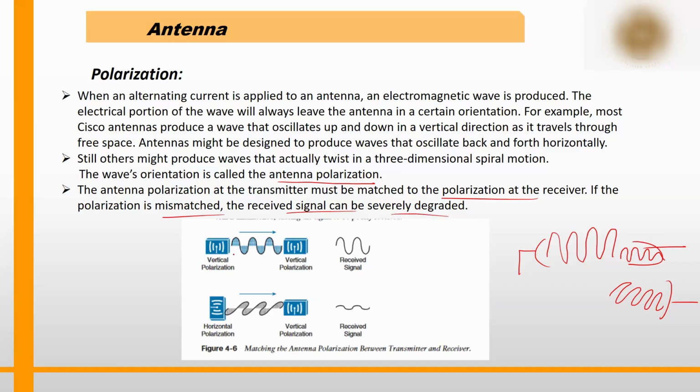So this is a vertically polarized signal, up and down like this. And this is sideways, horizontally polarized like this. So when you are sending the radiation, you can polarize it accordingly. Just remember the first session where you put a finger into a pond and it creates some ripples, right? It will create them horizontally or vertically. And on the receiver side also, the antenna should be oriented properly.